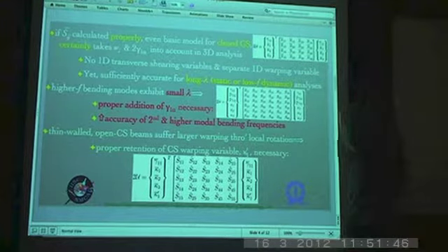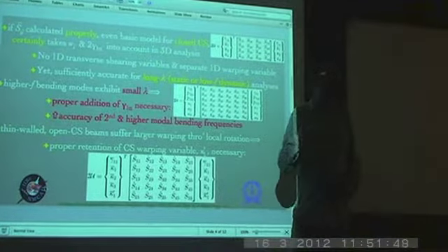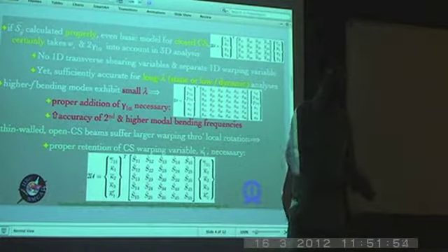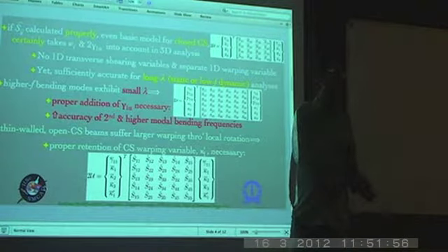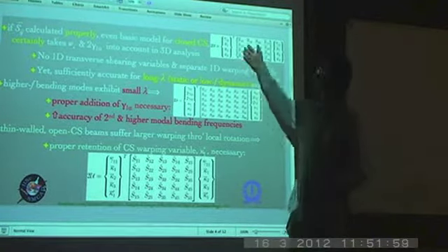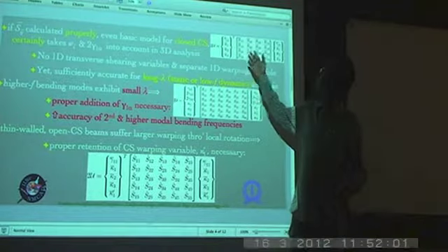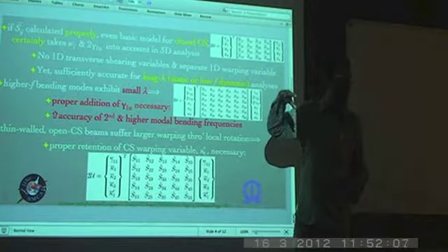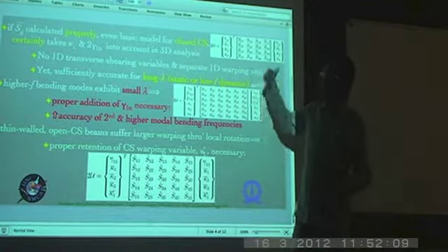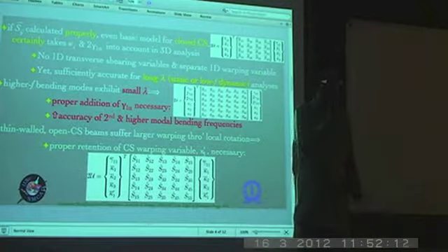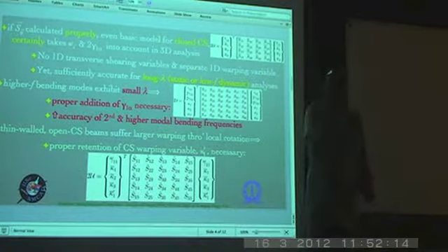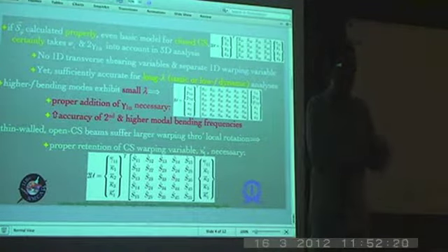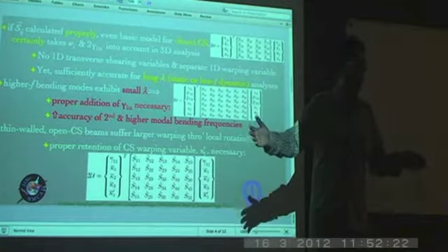No, see, gamma T. Yeah, see, those are higher order terms. What we are right now looking at is something just next to the 0th order approximation, the classical approximation. This of course directly is the classical approximation itself, but if these are calculated in a proper way, it could even be the first order approximation in some cases. But if you are going for even higher order approximations like second order or third order, then you will bring in the derivatives of the warping with respect to the larger dimensions. So in the case of the beam, it will be with W primes that we are looking at.